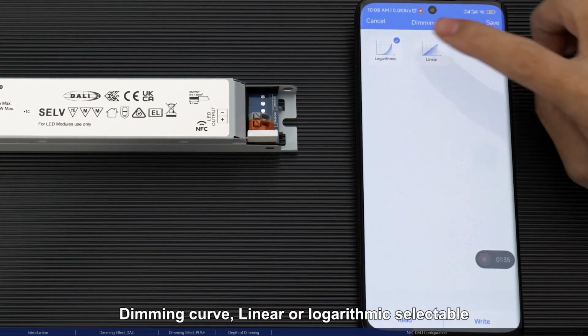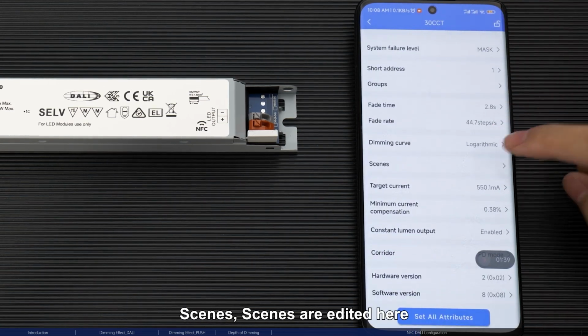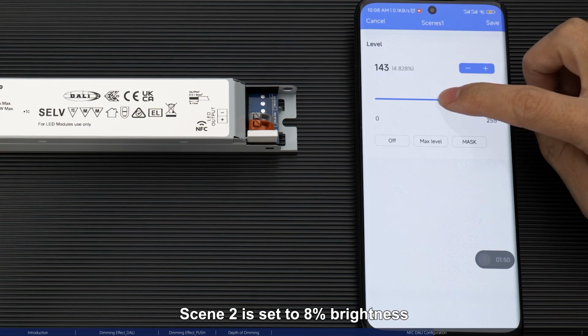Dimming curve, linear or logarithmic selectable. Logarithmic is a more comfortable dimming curve. Scenes are edited here. For example, Scene 1 is set to maximum brightness. Scene 2 is set to 8% brightness.